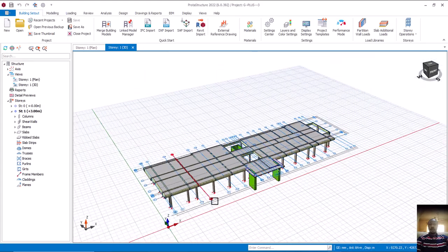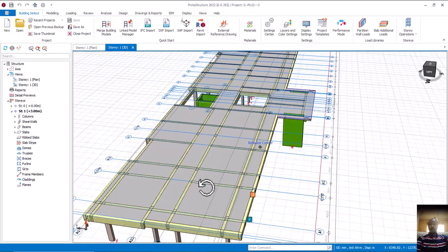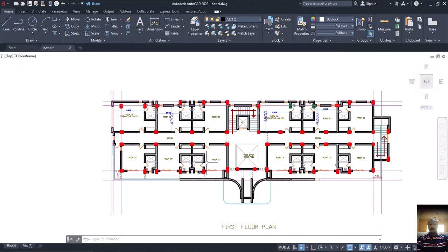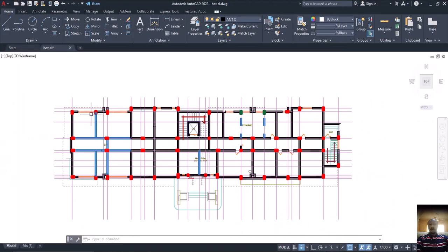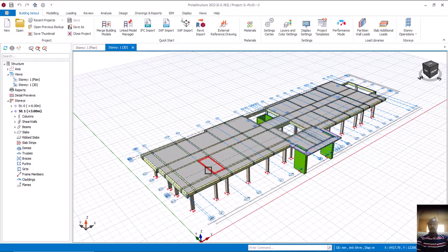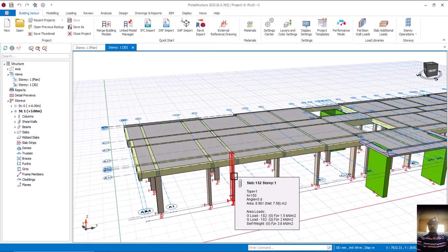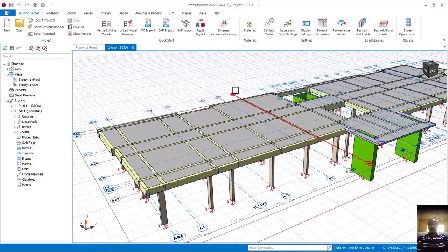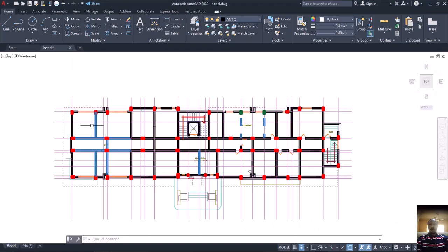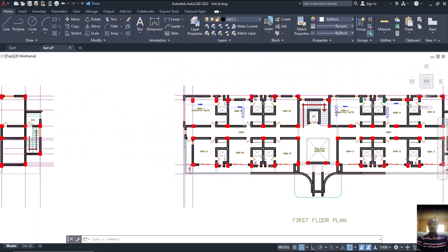Now we are going to continue with this video. You can see that last time we were able to model this ground floor. Ideally, some people will just come from here and only model this. They will model this particular one just as it is here, and once they are finished modeling this one, they will come here and do what? Insert story. That's to have another floor. Are we together now? When they insert the next floor, that's when they will begin to start working on this next floor that is projecting out here.